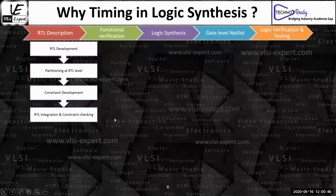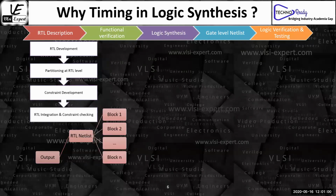So in this portion, the RTL integration, the output at this particular stage is going to be your RTL netlist, and in the RTL netlist you have the different blocks. Like I have mentioned, there are n blocks. Similarly, you will have constraints: the top level constraint and the block level constraint. Obviously the block level means the block level constraint of each and every RTL, so if there are n blocks, there are going to be n block level constraints, and there are going to be top level constraints. The top level constraint is about how the different blocks are going to interact with the top level. So that's what I'm talking about, the top level and block level constraint.